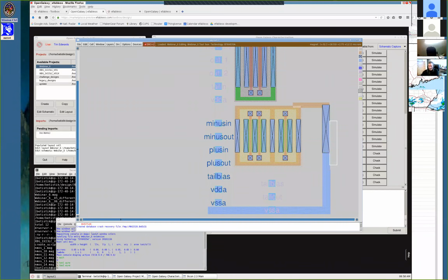Yes, I had put in the PDK something that would cause them to disappear, and I'm not sure why they're appearing in this case. My advice is, if you see them, ignore them. They are specifically to do with Magic's internal maze router algorithm. They're basically layers that you put down as hints for the maze router, and I don't really suggest using the maze router. It's not exactly the world's most optimal router. Like anything in Magic, you can always play around with anything that Magic has the capability to do.